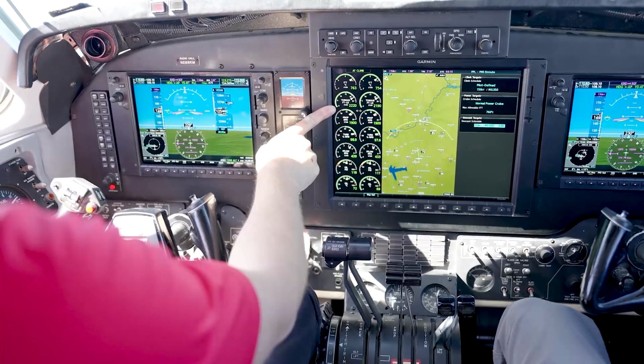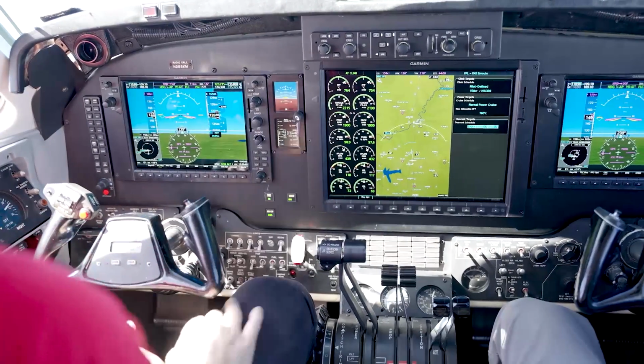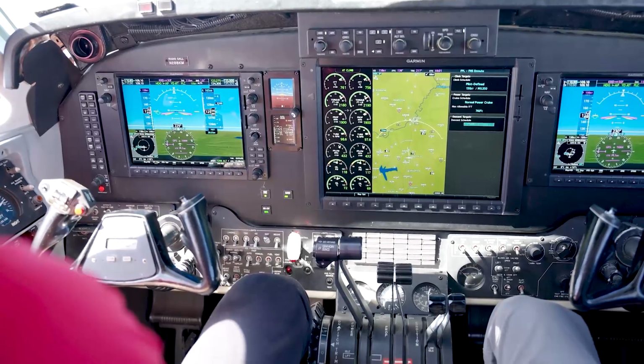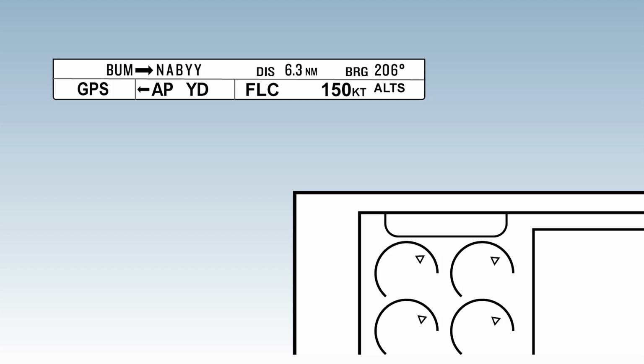For takeoff and go-around, the autothrottle will supersede the selected ITT limit to ensure engine power is not limited during the initial climb. If the autothrottle is disengaged and is approaching an engine over-torque or over-temp condition, it will engage to reduce power and annunciate AT max power in the autothrottle mode annunciator.